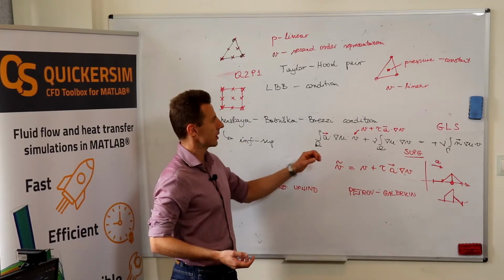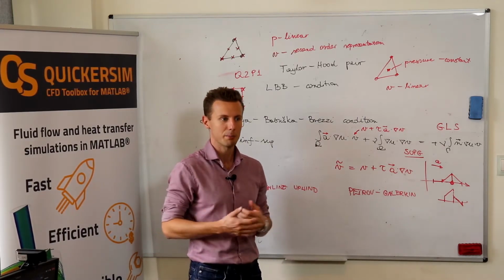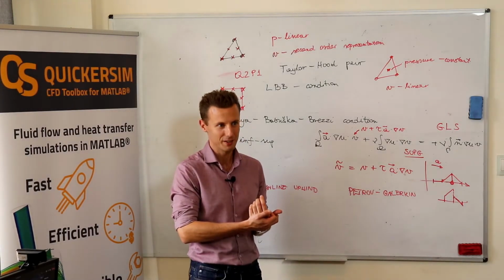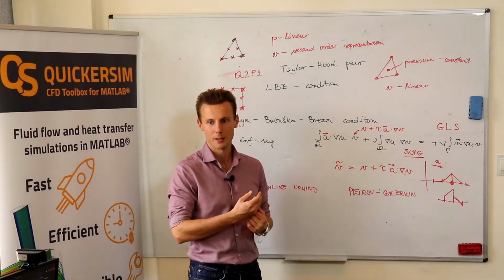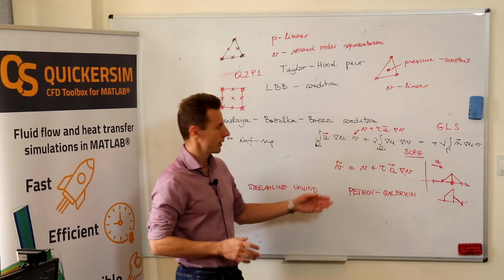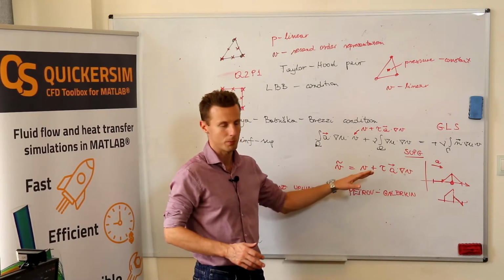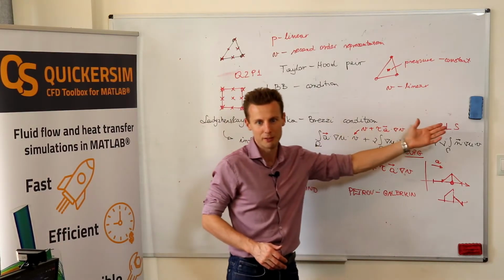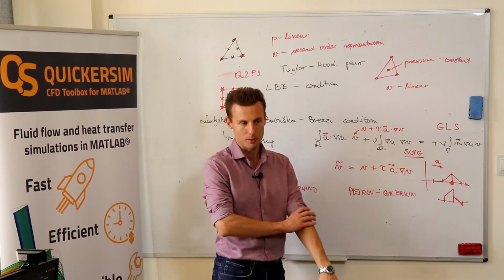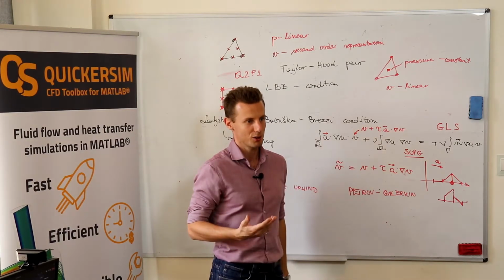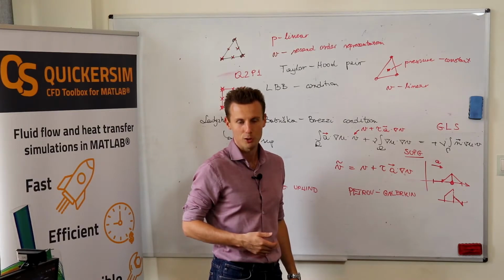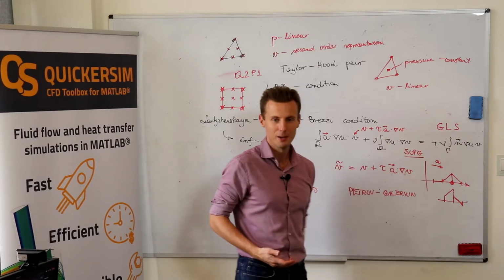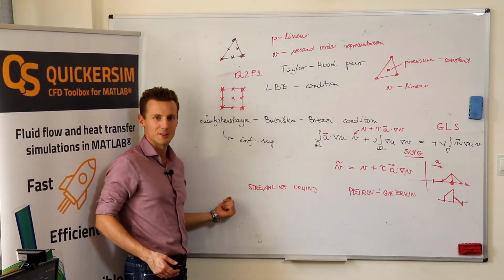But you need to start with the strong form and multiply it by some V. You need to multiply the whole equation by V and then integrate. So if you can choose such V functions, no problem, but you need to apply it consistently to each term in the equation. Then you do the integration. Such a method, if you reapply it consistently to each term, is called consistent SUPG.